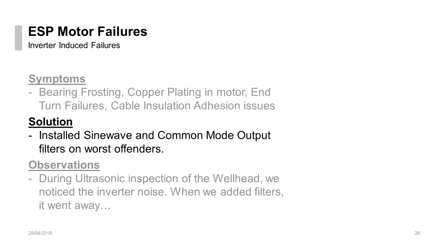So we started doing power quality analysis, brought in some subject matter experts, looked really closely at our electrical waveforms, and we realized, okay, we need to install these sine wave filters, but more importantly, we also have to install a common mode filter as well.